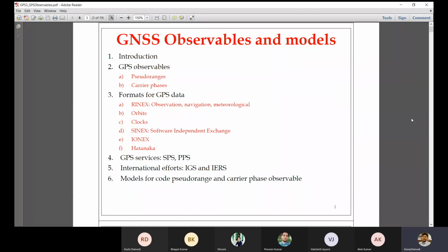And apart from that, people have also chosen to use a pair of GPS stations, where one is base and the other is rover. When they are working with code pseudo ranges, be it from CA code or P code, and they difference the code pseudo ranges collected at base and at rover for the same pair of satellites, this process is known as differential GPS. But when the carrier phase observations at both stations, base and rover, are differenced, it is called carrier phase relative positioning. So the terminology is a little different, depending on what type of observation you are using. I hope there is no doubt in that particular understanding.